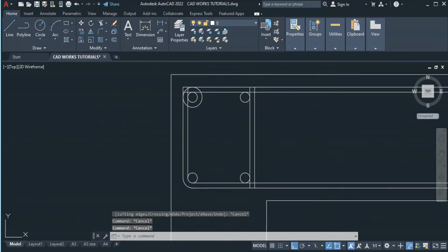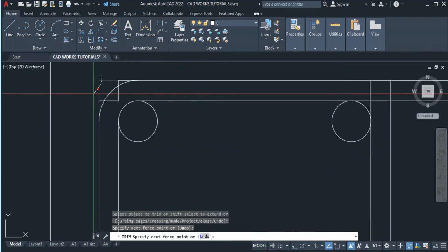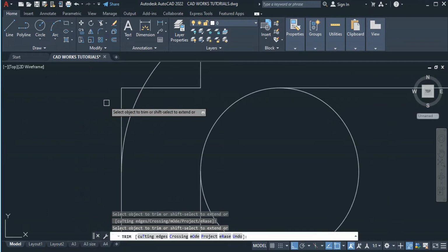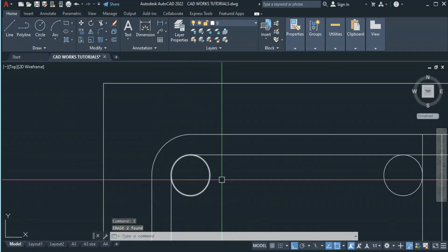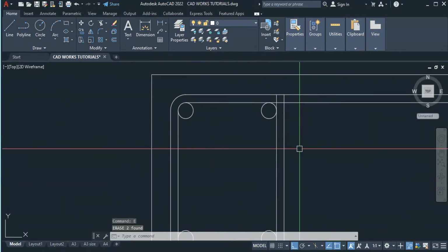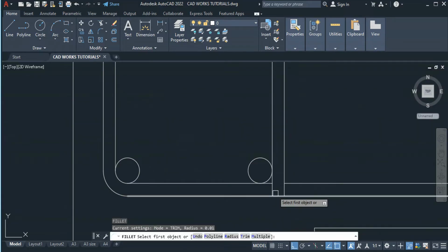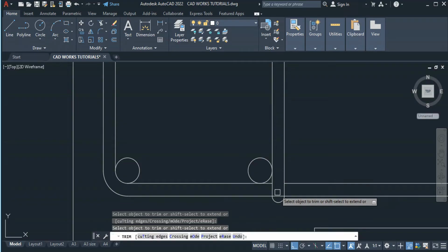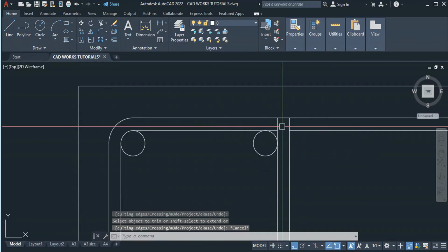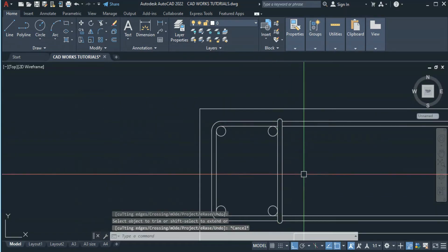Okay? So, ito naman. Remove this one. Okay? Itong sa labas. And then, these two lines here. And here. Erase this. Sobra. Okay, so once we're done, I'm going to erase this. And erase this, and then I'm going to press F for fillet para gawin siyang isang steel bar. Okay? Click. Then F, fillet on the opposite side. And then trim for fillet to make this as one object.